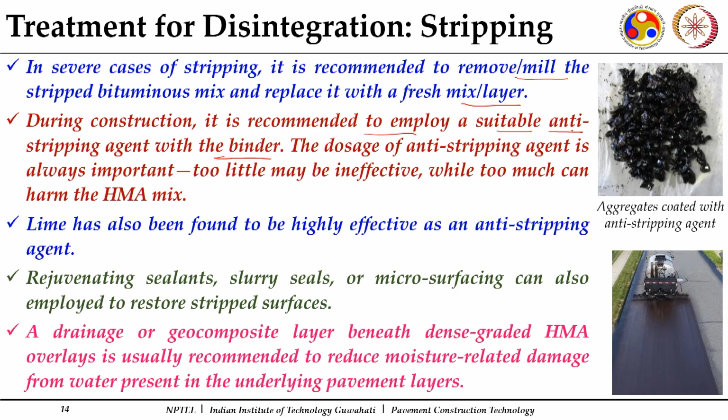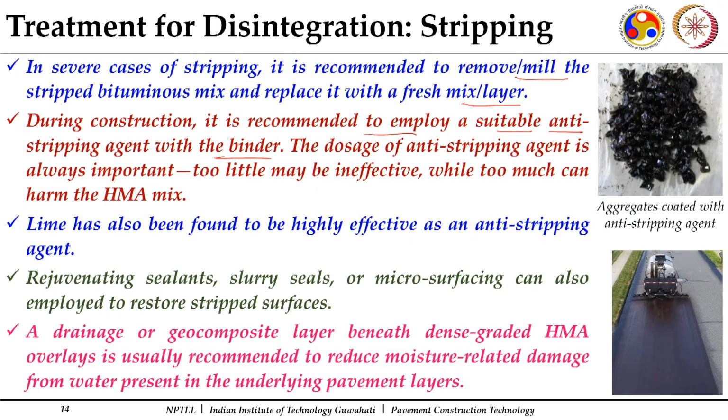Quite a good number of liquid anti-stripping agents are popular, but their dosage is important, because low doses may not be effective, and higher doses many times lead to a reduction in the strength of the mixes. So, the doses are to be carefully decided during the mix design.